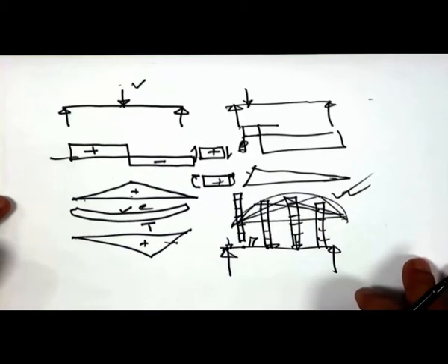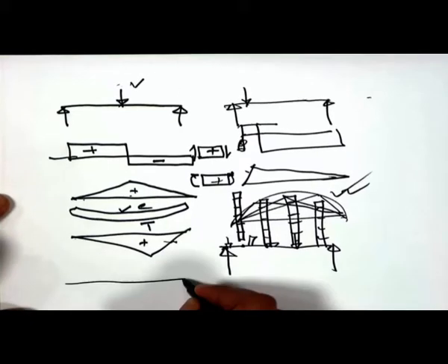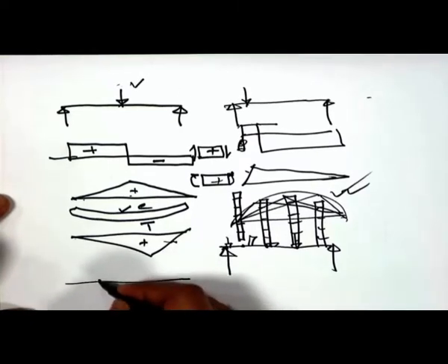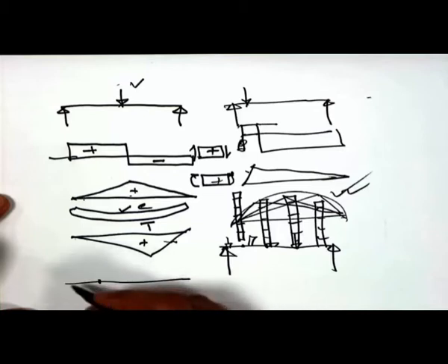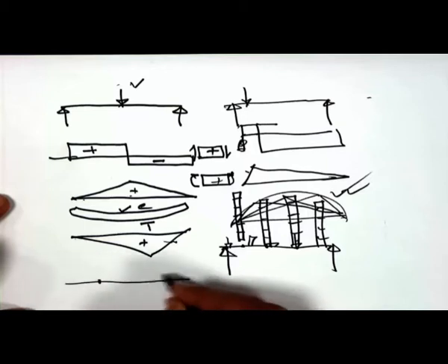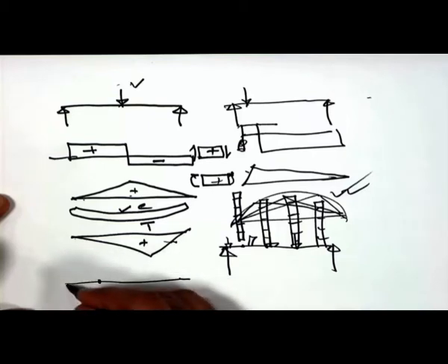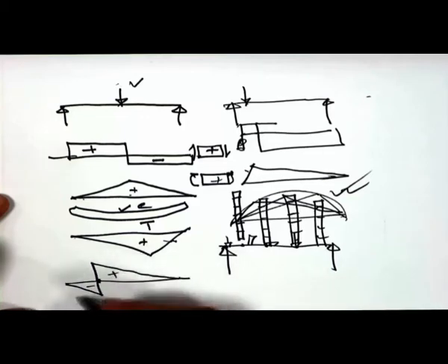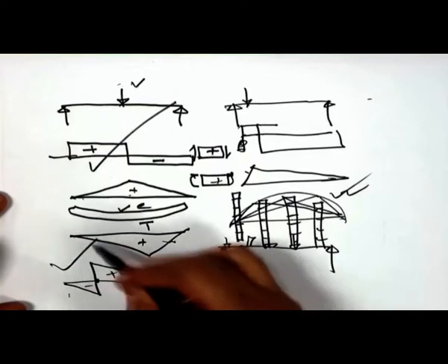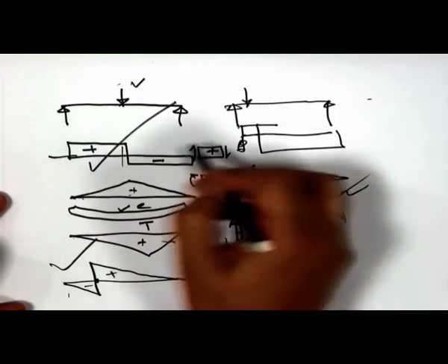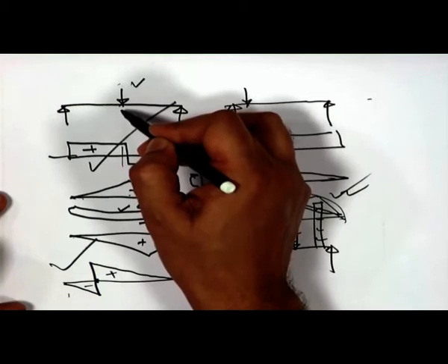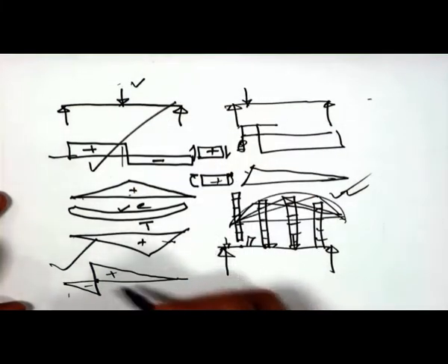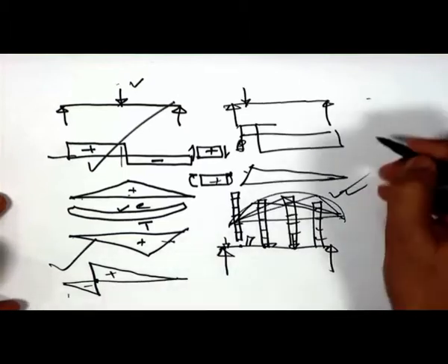So, is it not better that I select a location where I am interested in determining the variation, suppose the shear force, and then as the load moves over it, I plot along the length the influence line, the variation of the shear forces. Now this is the shear force diagram of the same beam with a constant position of the load, and this is the influence line diagram. I should have drawn it in the middle to comply. So, once again I am drawing it here.